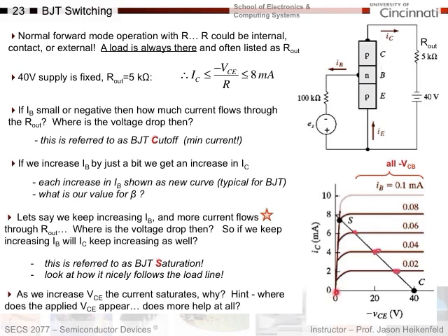And so for a given IB, I start to put voltage across the BJT, and now when I get to this point, my collector is fully reverse biased, it's ready to do its job, and if I put more and more voltage across the BJT, more and more voltage from the VCE here, then it doesn't have an effect because this is already reverse biased, and just like a reverse biased diode, its drift current, right? Drift current is not dependent on voltage because once you've created the cliff, the carriers fall off the cliff all the time anyway, okay?